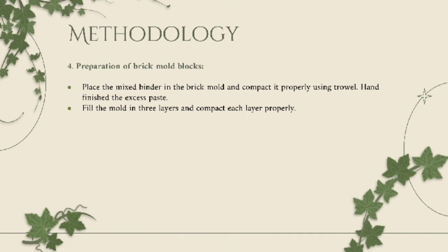Preparation of brick molds. Place the mix binder in the brick mold and compact it properly using a trowel. Hand finish the excess paste. Fill the mold in 3 layers and compact each layer properly.